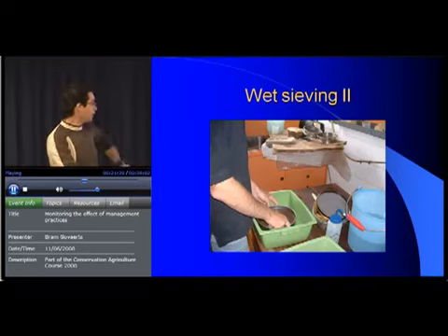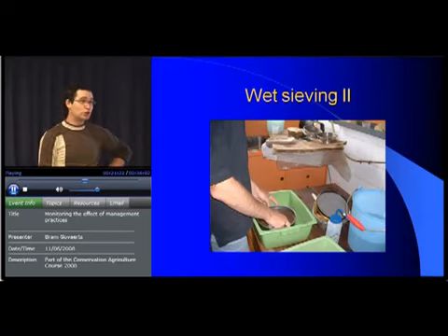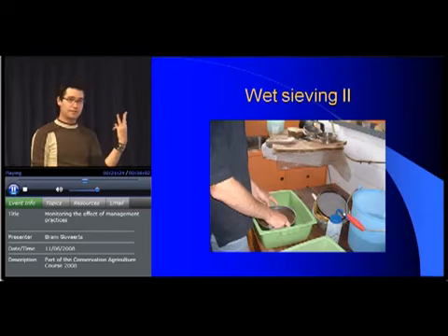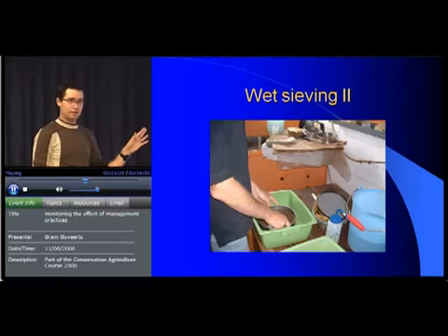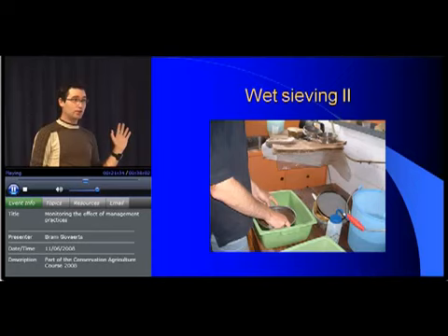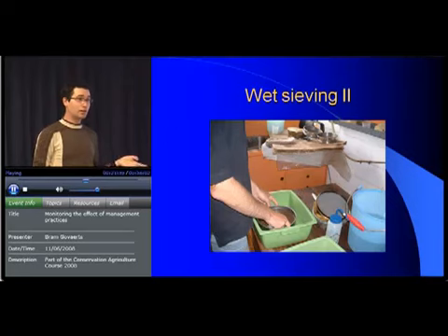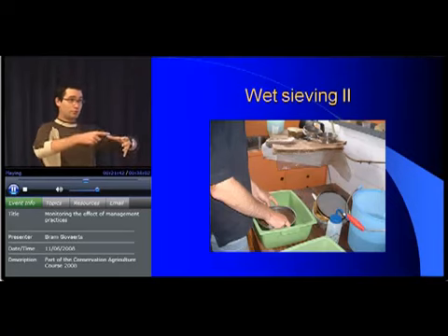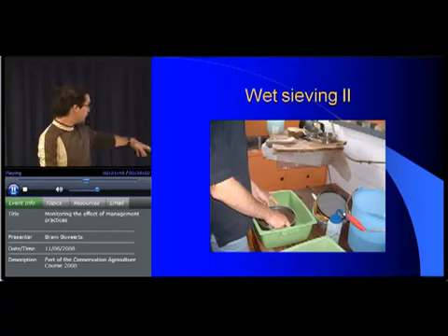This one, you can perfectly do, right? You call the local university and you ask for 3 sieves. That's about it. Same thing we did in Ethiopia. We had 3 sieves, that's about the only thing you need, and a drying oven. The rest you just invent. What did I do? I just asked the local bakery factory to give me some of those, because these are the plates you use to make cookies, no?